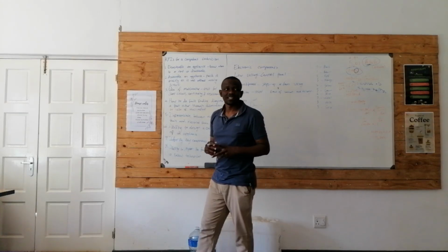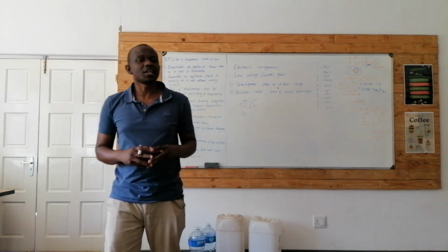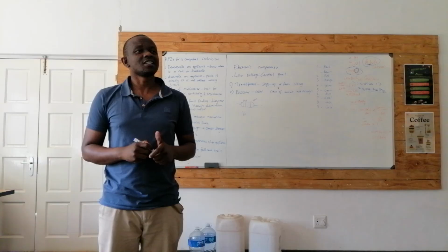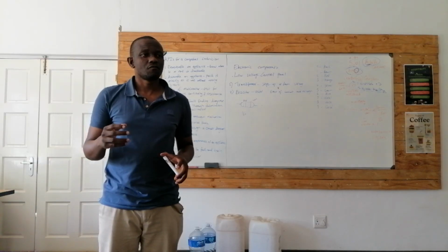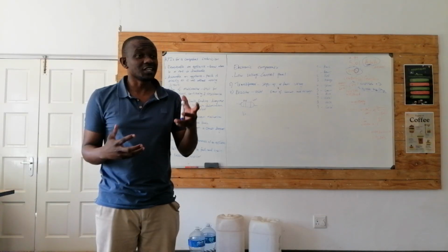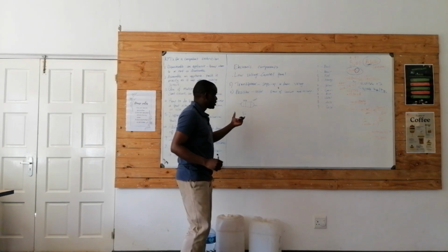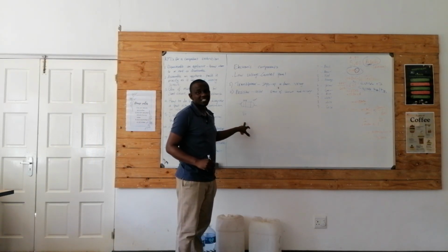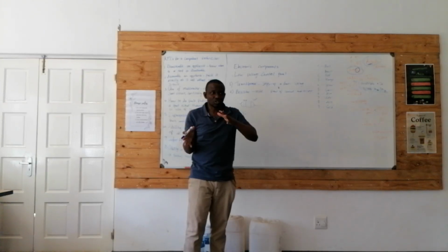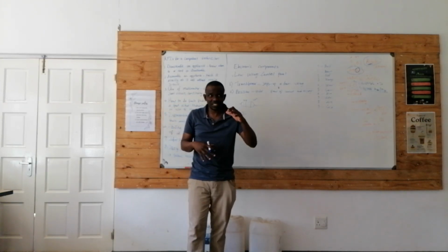So those colors represent the resistance of your resistor, the value of the resistance. When you use a multimeter, you're going to get roughly the same value, and tolerance means between this and that.